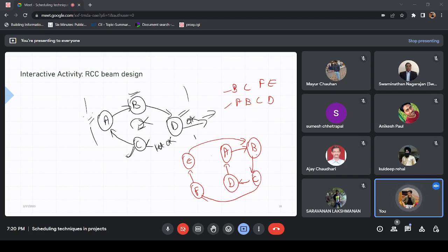Or in this case, you just simply do what sir said. You break in such a manner that maximum loops get broken with minimum tears. So now what is happening is that B is giving information to C. Only if you determine what is happening at this information exchange, you can do away with two loops, right? Only at one point you have to worry much and it will solve your problem. So this is how you determine the minimum number of tears.